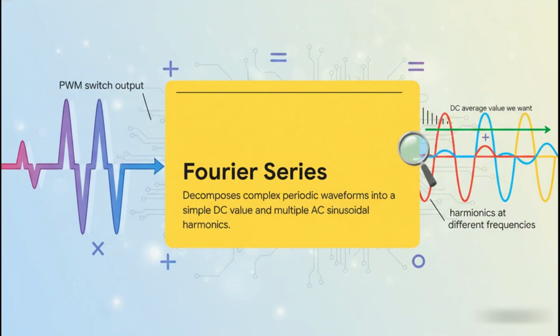It's this amazing piece of math that lets you take any messy repeating signal, like the output from our switch, and break it down into a bunch of simple, clean sine waves. The analogy of a musical chord is perfect. The Fourier series is what tells you every single individual note being played in that complex sound. This is absolutely critical for calculating power and, more importantly, for designing the filters to get rid of all the